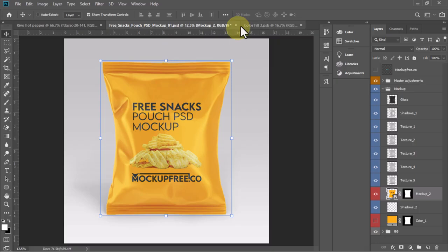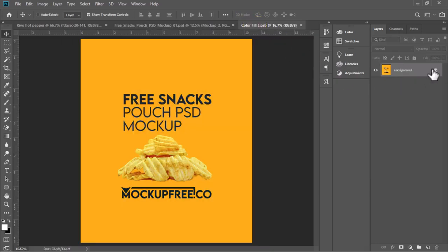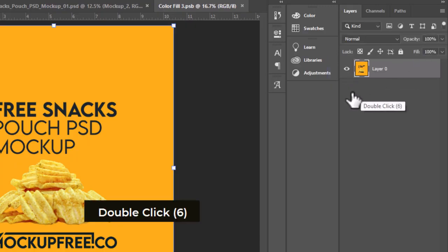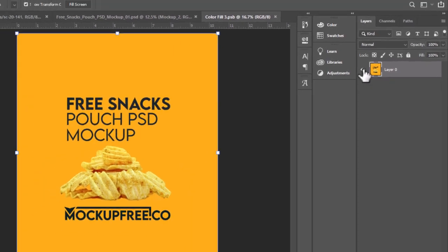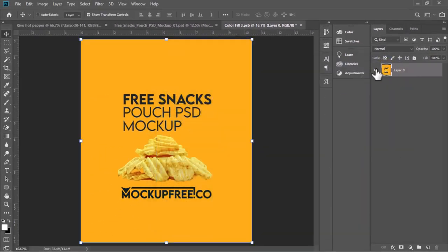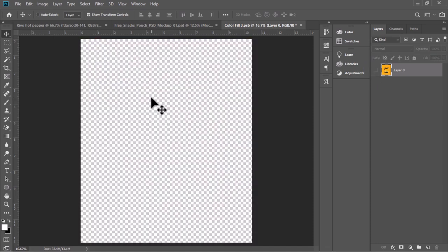So just to close, and then let's do the magic together. So I just have to uncheck this thing. I turn off the eye icon. Why is it not turning off? Oh really? It is because the layer was locked. I've now removed the lock, so I can actually uncheck, and then it is great.